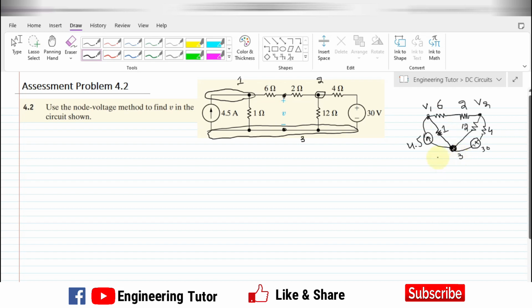So this is node number 3. As I told you earlier, we have to select one of these nodes as a reference node. The selection criterion more commonly used is to identify as the reference node the node in which most of the branches are connected. So here node 3 is the node which possesses those characteristics. So selecting it as the reference node, we have this circuit.